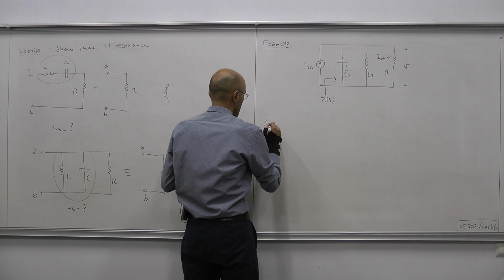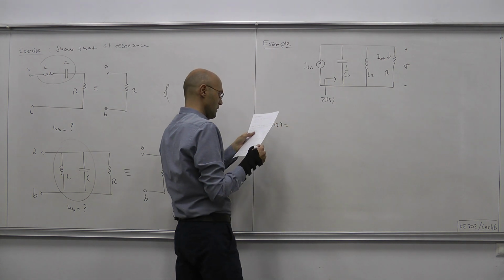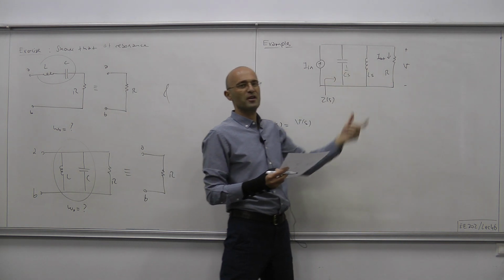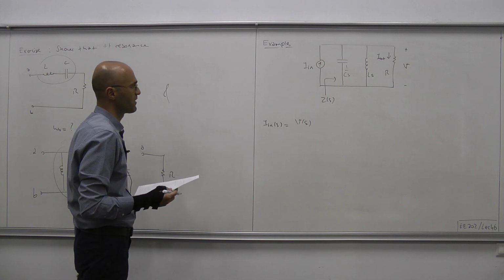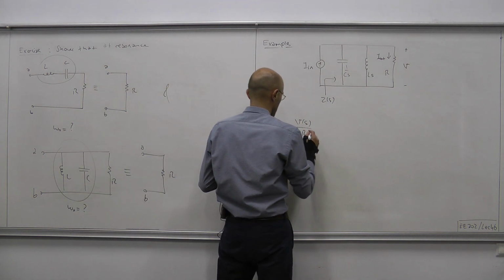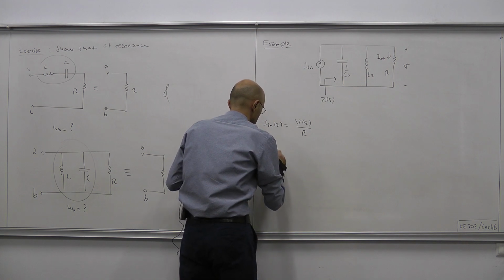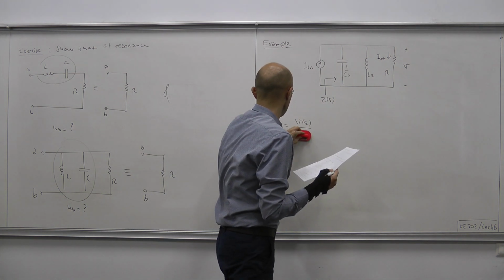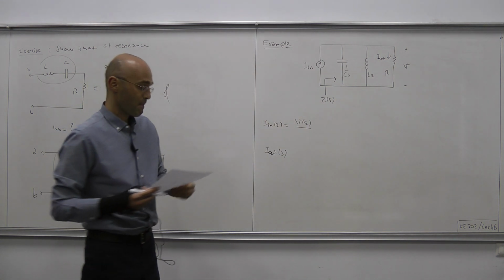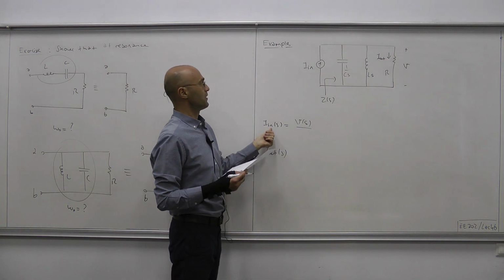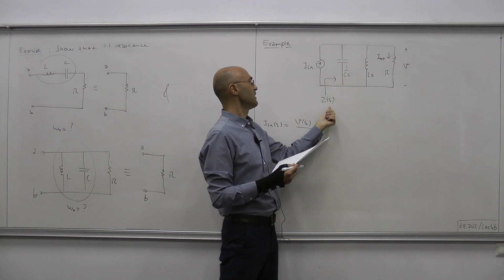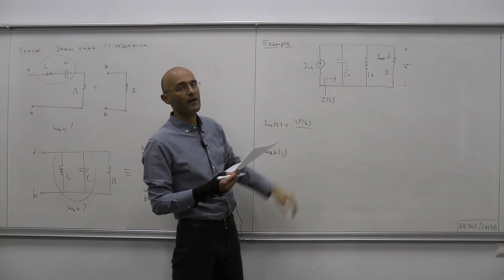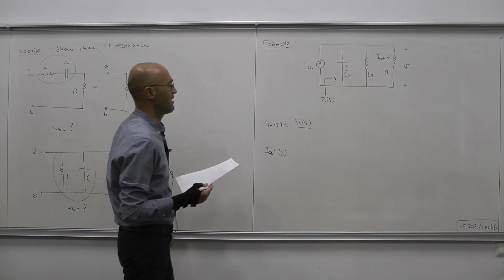The output current equals the voltage across the terminals of the resistor. Since everything is parallel, there is a single voltage, so that's V over R. Excuse me, that was the output. Now the input current, since this is the driving point impedance Z, is simply that voltage, which is also the voltage that appears across the terminals of our input, divided by the driving point impedance.